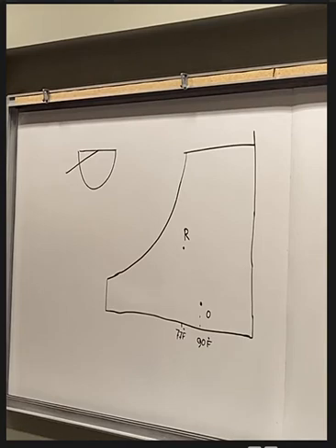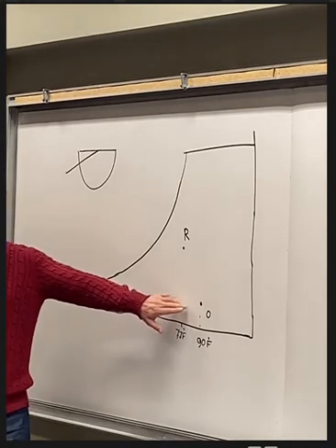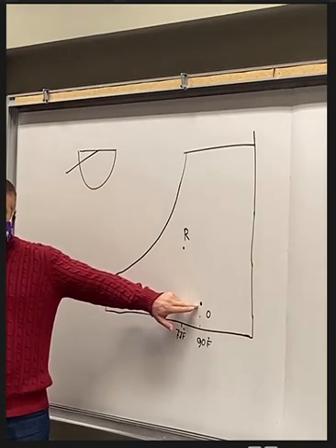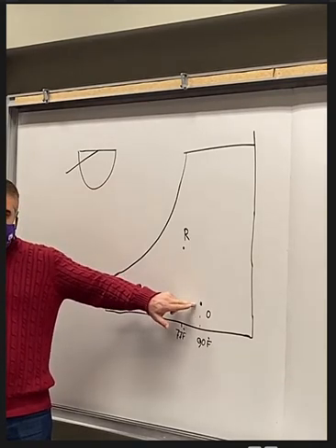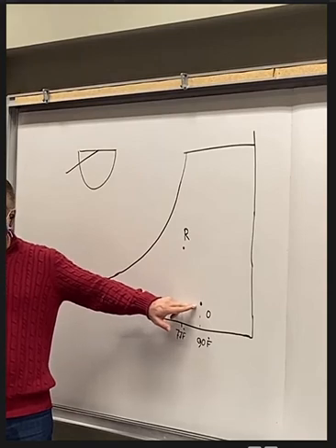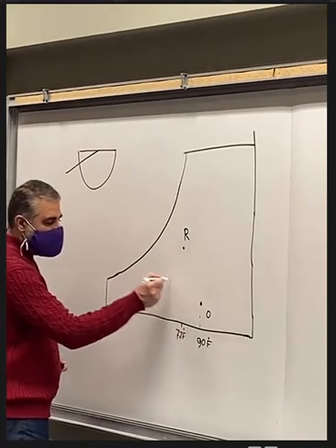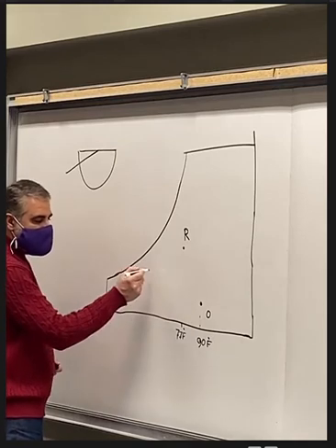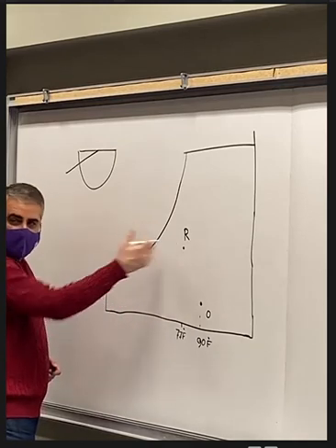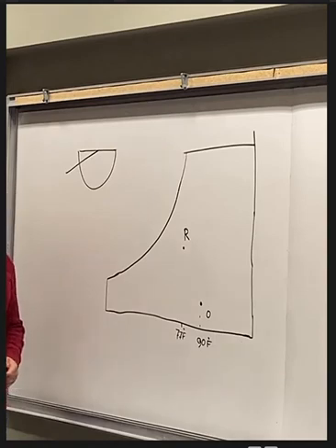Since this point is dry and hot weather, most probably I think an adiabatic humidifier will be a good solution for this question. Because if we allow the air to go through an adiabatic humidifier, it will leave at lower temperature and higher humidity, and then we can supply the air to the space to satisfy the cooling conditions.